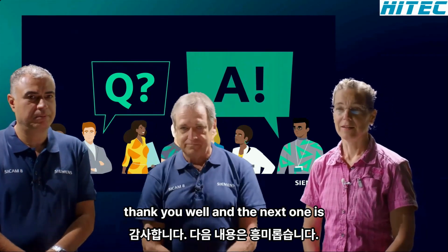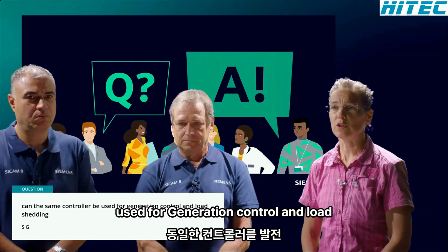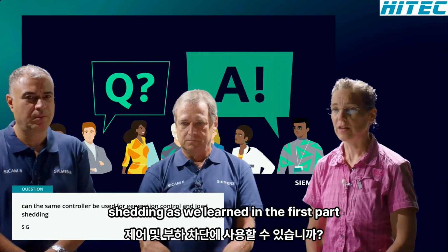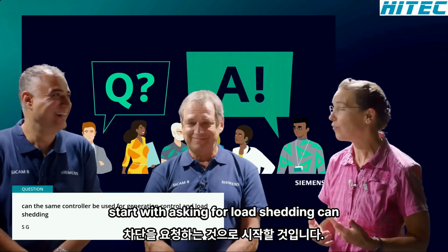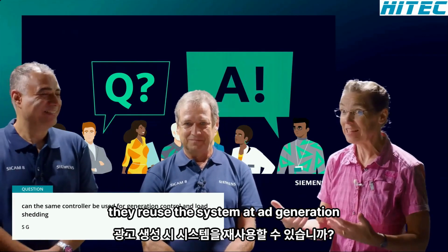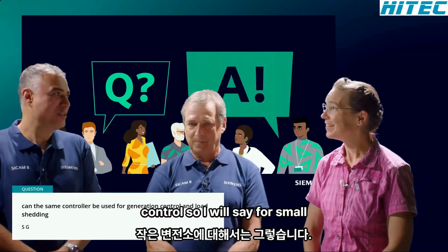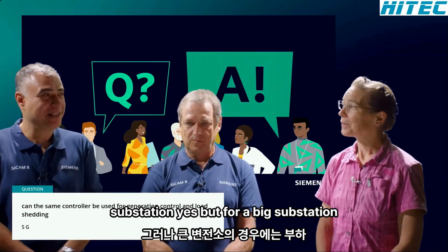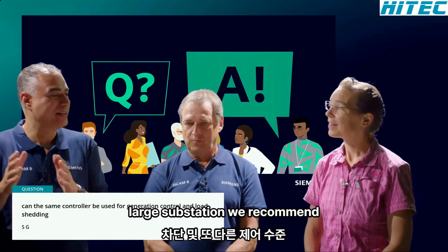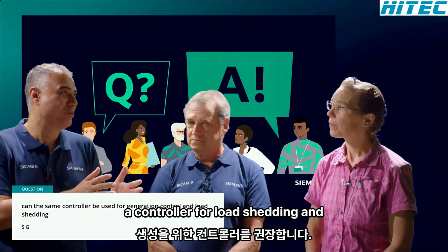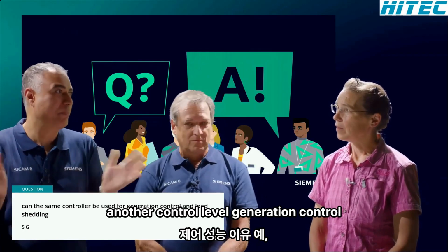Thank you. The next one is interesting. Can the same controller be used for generation control and load shedding? As we learned in the first part of the webinar, a lot of customers will start by asking for load shedding. Can they reuse the system and add generation control? I would say for a small substation, yes, but for a large substation, we recommend one controller for load shedding and another controller for generation control, as we separate out the controllers.